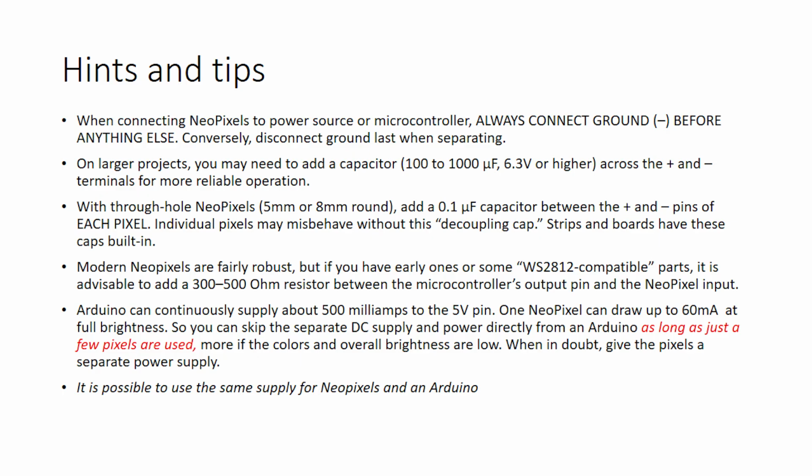Power supplies sometimes ring. And for that reason, it's a good idea to put a big capacitor across your NeoPixel chain. And that way the big capacitor's holding a charge. And when the NeoPixels start drawing extra current, the capacitor supplies it. And the capacitor starts slowly discharging and your supply starts recharging the capacitor, and it smooths out the draw, the stepping up and down that the current draw is doing because of these LEDs all coming on and off in sequences.